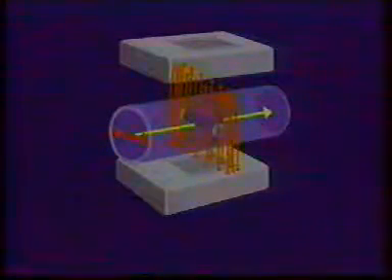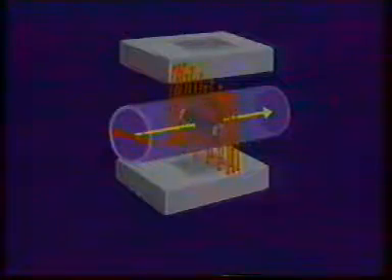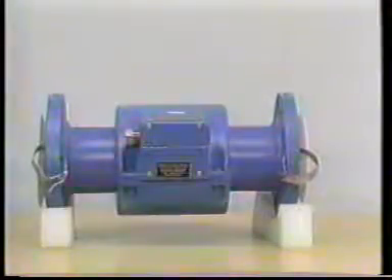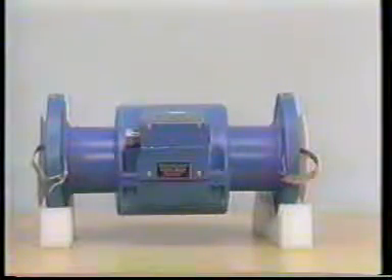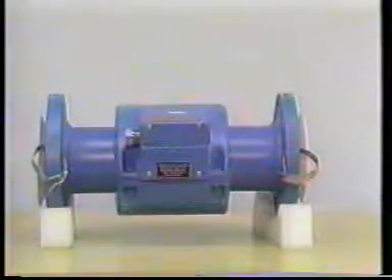The induced voltage is in a plane that is perpendicular to both the magnetic field and the motion of the conductor. The process fluid passes through the magnetic field induced by electromagnetic coils or permanent magnets built around the short length of pipe called the metering section. Because a magnetic field is used for induction, the metering section must be made of non-magnetic material. Further, if it is metal, it must have a lining that serves as an electrical insulator for the flowing liquid.